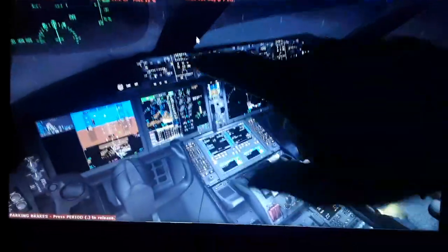So this will command the engines, the FADEC and the electronic engine control of the engine. So we have this when we command the airspeed guidance from the autopilot flight director system panel, and the auto throttle will command the airspeed of the aircraft in flight from takeoff, climb, cruise, descent, approach and landing, depending on the altitude of the aircraft in flight and its configuration. So we're gonna see also that. We're gonna have the airspeed selected here.